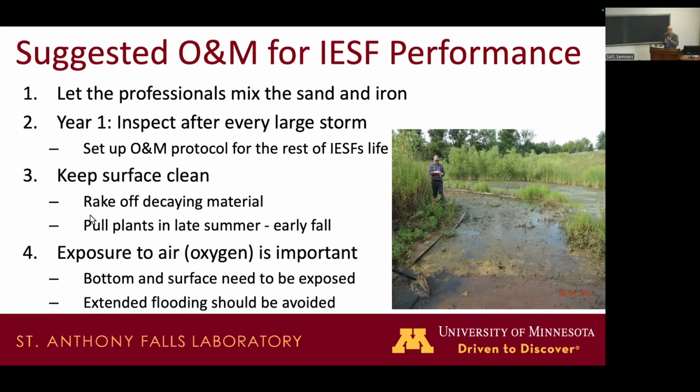It takes about 5 days, or sometimes longer, but 5 days is a pretty good number. After 5 days, you have ferrous iron because you have zero dissolved oxygen. That ferrous iron releases the phosphate, so basically you're supplying all the phosphate that you have captured to your water body. So extended flooding should be avoided. That's important to remember.